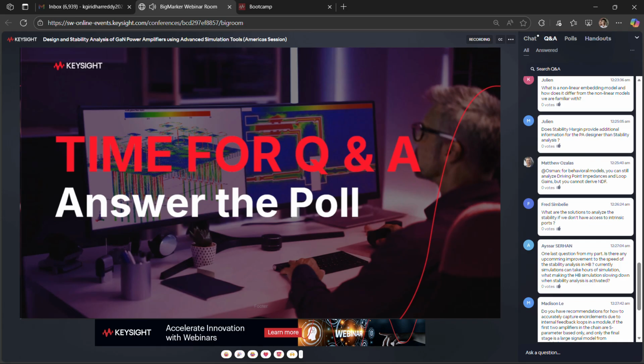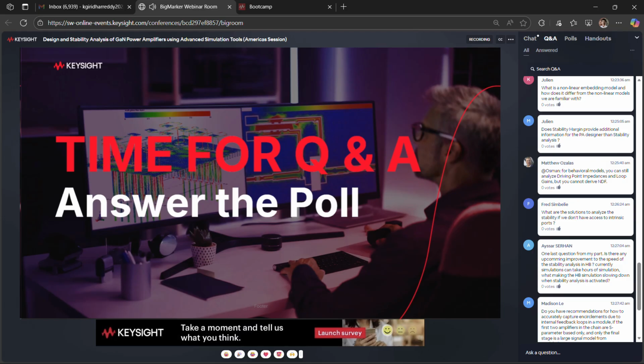So with Nexus, that tool comes with built-in Python APIs. And we also have in Nexus virtual probes. So you can place virtual WS probes instead of breaking up your circuit and placing them in. So if we combine those two things, that means that you can go through your design. Effectively, you can detect all of your devices in an automated fashion in your schematic using Python. And then you can add virtual probes to all of those nets that touch the device itself.